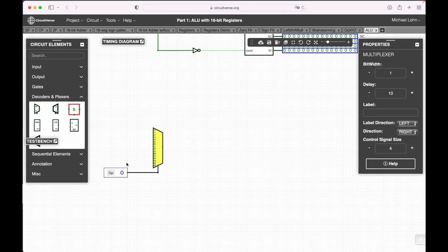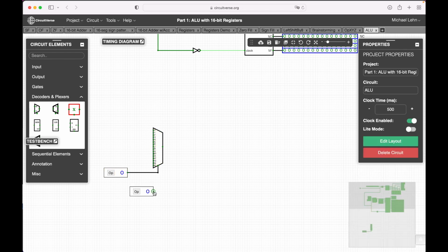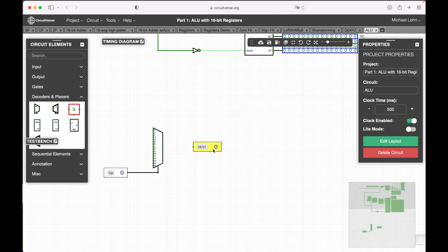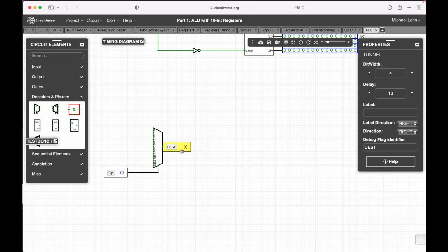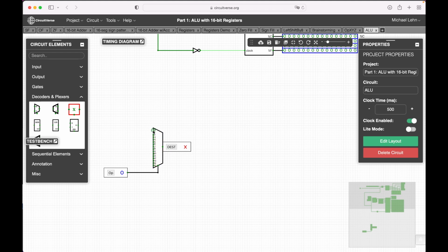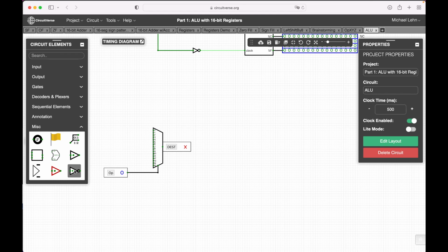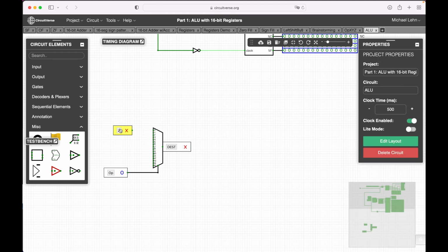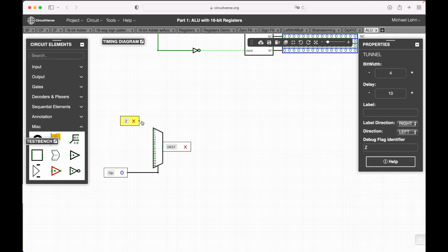So the control signal size is always 4-bit. Now this is the column for the destination. So I just copy this, change the name to dest all uppercase, and then click on it, change to 4, so properly correct. Direction right. Arrange it nicely, we need lots of space otherwise. And now here I have to select that in the first row, in the first column, this should get this set, this field from the instruction. So this should be set. Okay, name was typed in correctly.